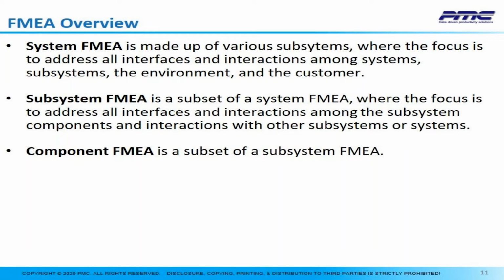The third is the component FMEA. It is a subset of a subsystem FMEA. An example would be the brake pad, which is a component of the brake assembly that is a subsystem of the chassis system.